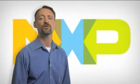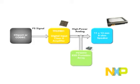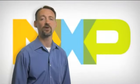The solution we will show you is based on using the output of the chipset, or codec, to drive the TFA9881. Or you could substitute the TFA9882. In cases where you need robust system-level ESD protection, the PESD5V protection diodes are a perfect choice, as they are available in small packages. The demo setup you see here is the TFA9881 with a controller board attached to a computer, which helps generate the data stream and the embedded control tokens we'll be talking about in a moment.